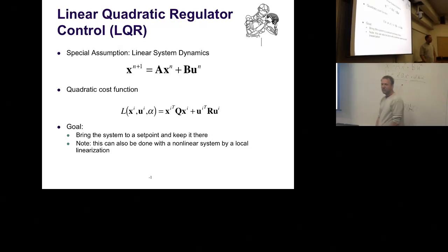So these systems are called non-minimum phase systems in the control language. But essentially, the idea is that in order to reach the goal, you have to go away from the goal first, which is weird. So just coding this with a simple PD controller will normally not work for you. At least you have to set the gains in a very special way to make it work. Let's put it this way: if you just play with gains, you will be very, very unhappy. But this is why this problem has been studied so much. It's a standard textbook example. It's cool. And people can basically solve it with LQR control. This kind of optimization comes up with the right solution.